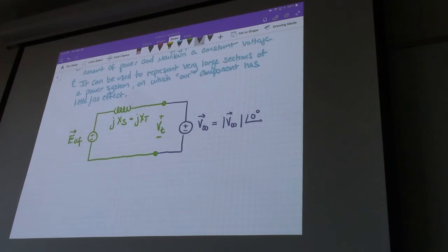And we'll see that in a lot of power system problems. For almost anything except longer transmission lines, the resistance is often dropped. Well, obviously, for loads, we don't drop it, because a small resistance value corresponds to a relatively large load. They'll be drawing a lot of power. So the main resistances you'll see in a circuit model that we're going to be looking at are resistances representing the loads, and resistances representing very long transmission lines. Often the internal resistance of transformers is neglected, and the internal resistance of the synchronous machines is going to be neglected, just like you said, because it's not having much of an effect on the answer.